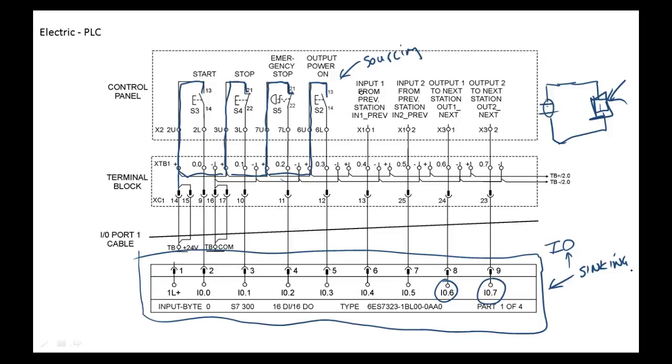If you take solid state, you'll understand that. But we have two types of solid state sensors. We have one called PNP, and we have one called NPN. The easy way to remember: P means positive, so PNP sensors are sourcing. NPN is sinking. That means if I have a sinking device, I have to hook it to a source. Remember that, because when you buy these sensors, it'll be listed either NPN or PNP, or sinking and sourcing.